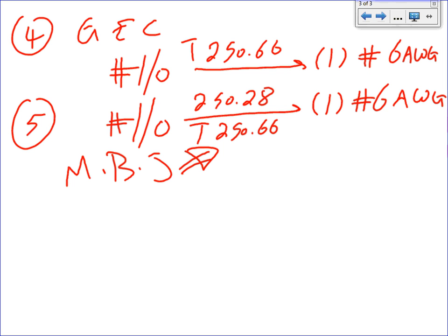A grounding electrode conductor does not need to be more than 3/0. Can you make it 4/0? 250? Copper as much as you want, but it doesn't need to, based on the code, be more than 3/0. We did medium voltage substations, guys. The standard was 4/0 copper buried underground for the grid, a foot by a foot grid of copper under the substation, the grounding grid, or grounding mat.